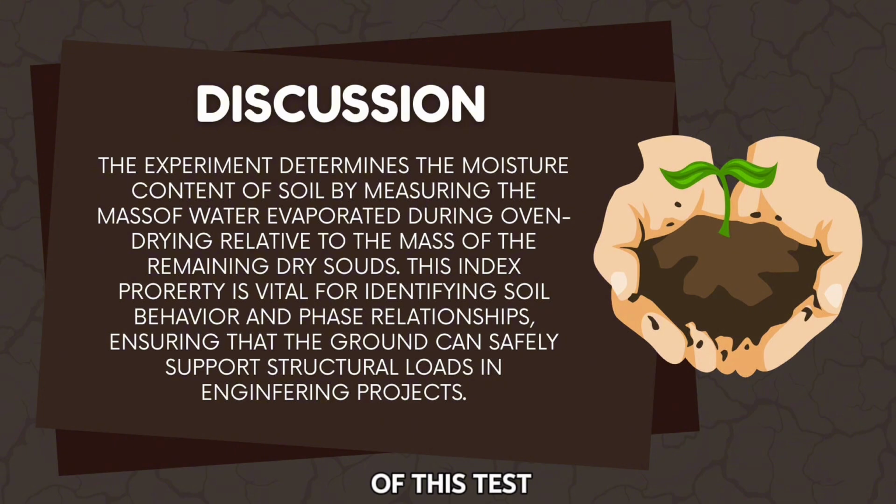The results of this test are also essential in establishing soil phase relationships and in performing other laboratory analyses such as compaction, Atterberg limits, and density tests. Proper determination of moisture content helps ensure that the soil can safely and effectively support structural loads in various engineering projects, including buildings, roads, embankments, and foundations.